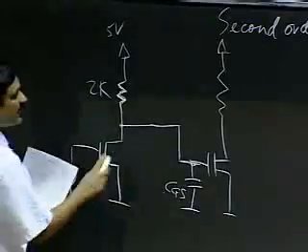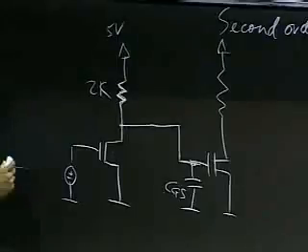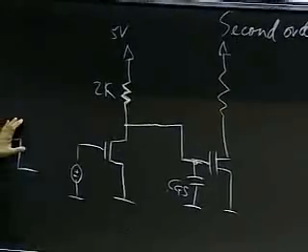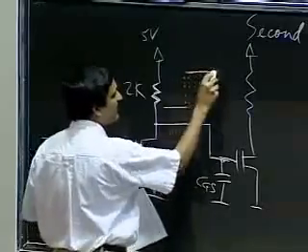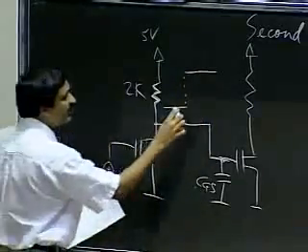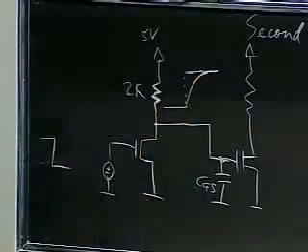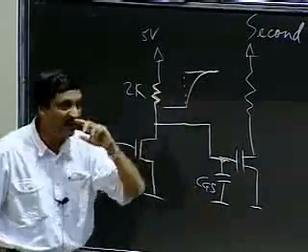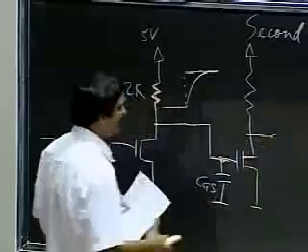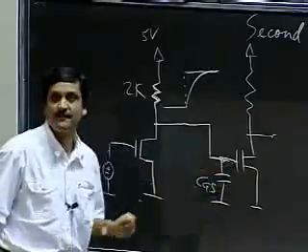And we saw that if I had a step here that went from high to low, then out here I would have a transition that instead of going up rapidly like this, would transition a little bit more slowly. This transition was characterized by an RC time constant, and this is what gave rise to a delay in the eventual output. So that's what we saw previously, a single energy storage element.